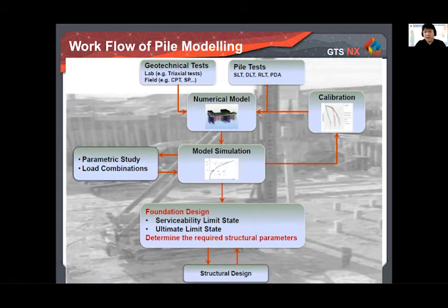And you run your simulation, and you will get results in terms of deformation, stress and strains, and force in the piles. You can also run a parametric study, varying the layout of the piles, the diameter and the length as well, and also different load combinations. If you have different combinations, refer to structural load, wind load, earthquake load, and combinations of these.